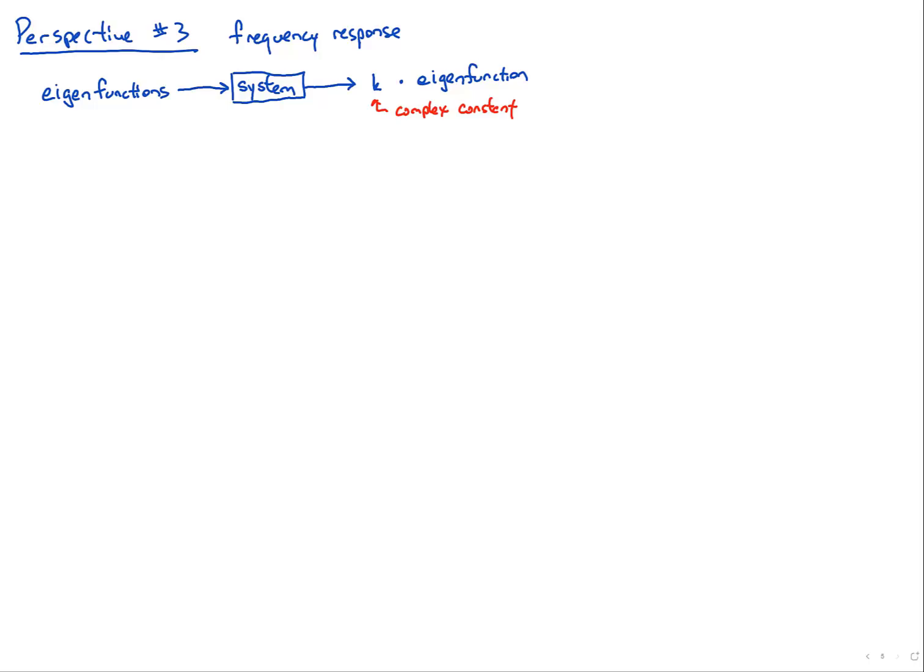And that's really surprising. If you put a square wave into a linear system, you won't get out a square wave. If you put in a triangle wave, you won't get out a triangle wave. You'll get things that look fundamentally different. But if you put in a cosine wave, or a complex exponential, or a regular real exponential, you'll get out the exact same shape, just scaled. And the most common example of an eigenfunction, which is of real theoretical use, especially in graduate school, is this guy, e to the j omega naught n.